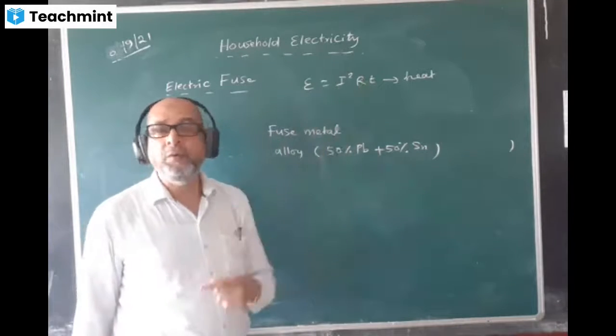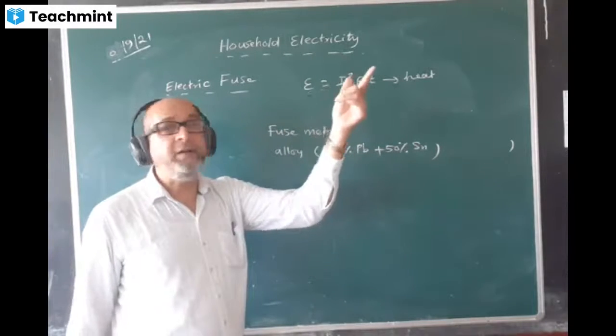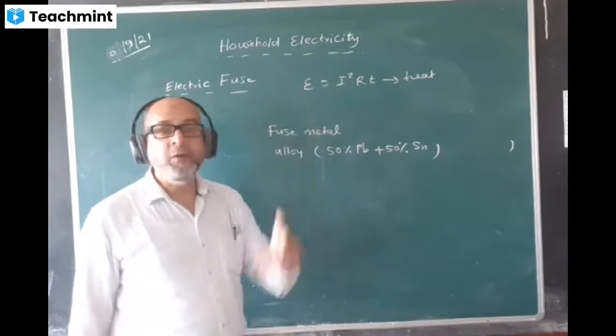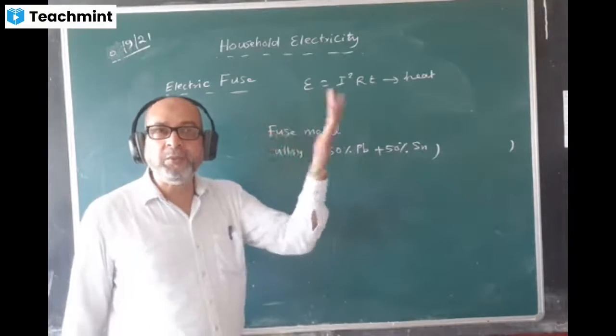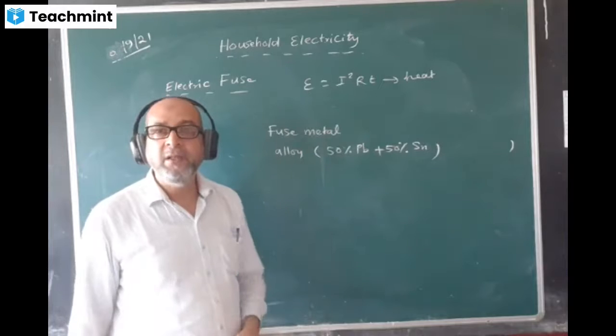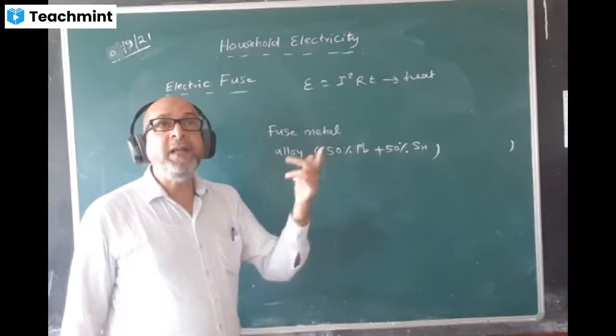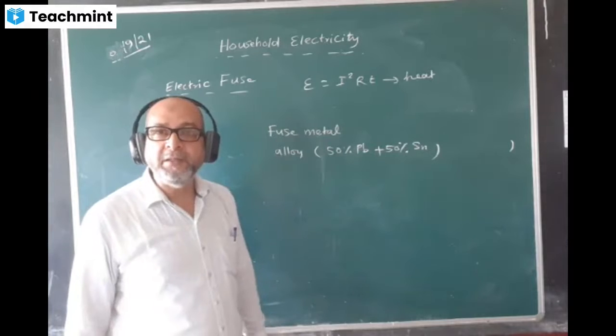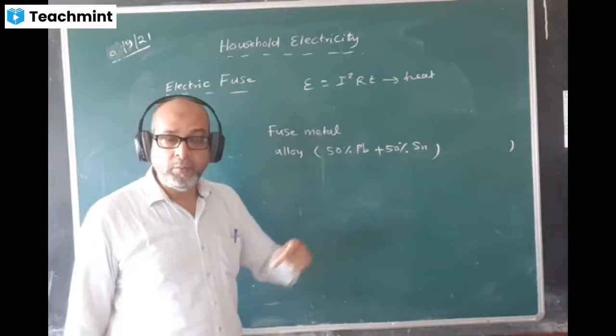Copper wiring is good because we don't want the wire to heat up so much. We want high current to run through it with less obstruction, with less resistance. It also has a high melting point, so the wire can withstand the heat generated in it. That's why we use copper wire at home.